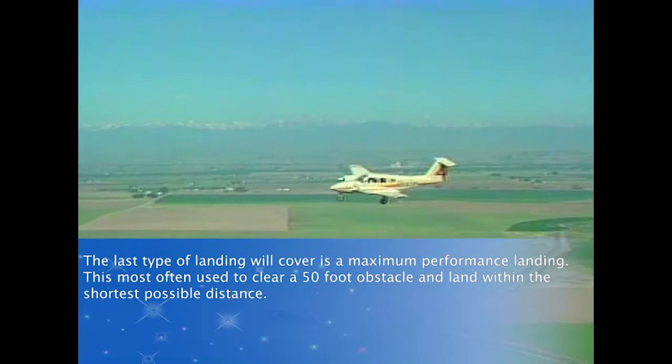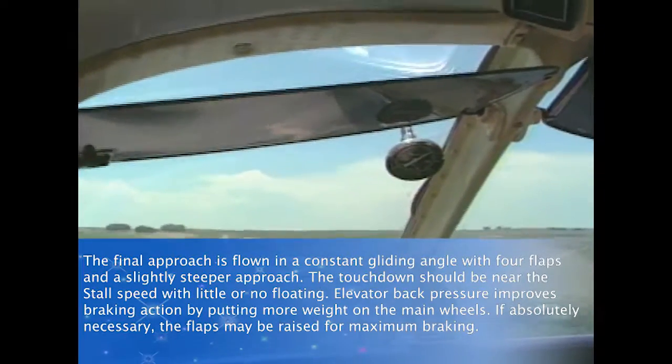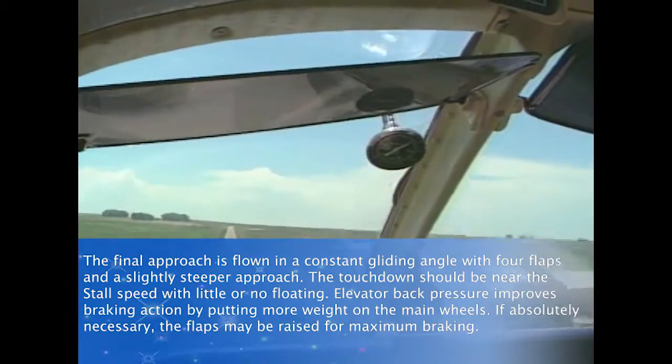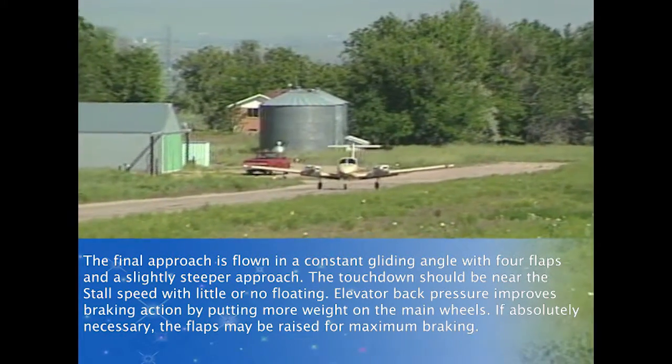The last type of landing we'll cover is a maximum performance landing. It is most often used to clear a 50-foot obstacle and land within the shortest possible distance. The final approach is flown at a constant glide angle with full flaps and a slightly steeper approach. The touchdown should be near the stall speed with little or no floating.